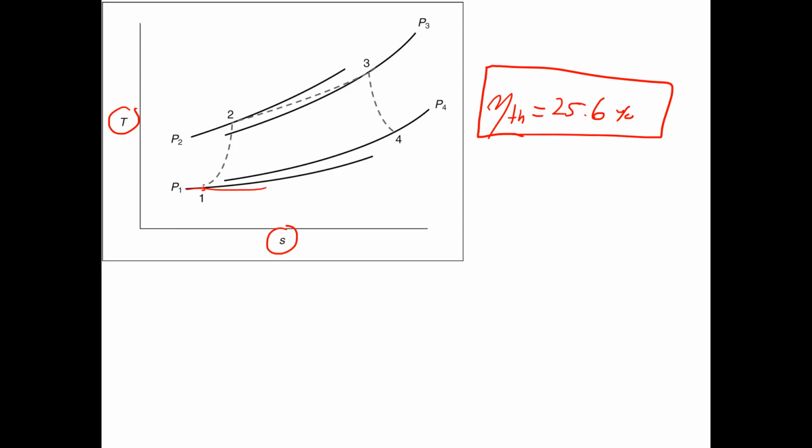You can see the pressure going into the compressor, non-isentropic compression up to 0.2 coming out of the compressor. Then that goes into the combustion chamber, but there's a 3% drop in pressure. So that's coming out of the compression chamber. Then we have an expansion through the turbine, again where the process is non-isentropic, so we have some entropy production during that. Coming out at T4, that's rejected to the atmosphere. Then we have T1 coming in, which is being taken in from the atmosphere.